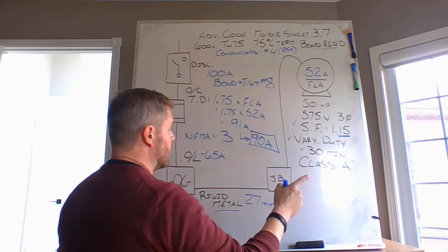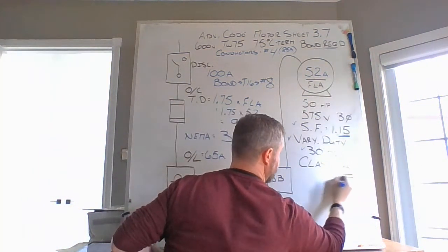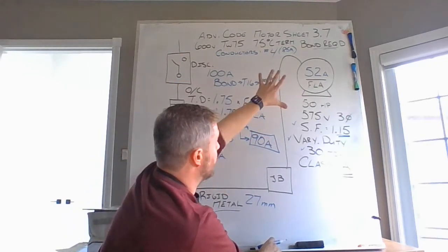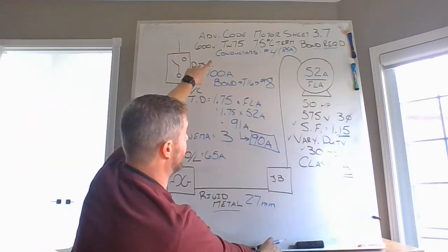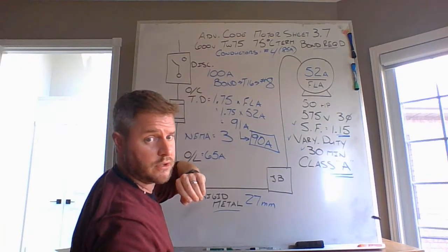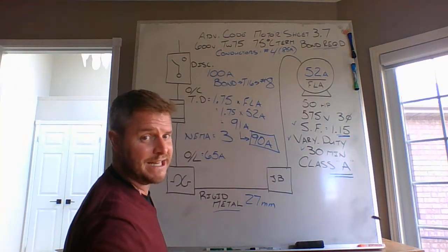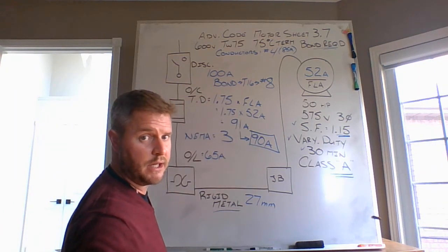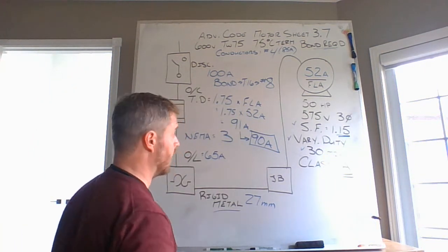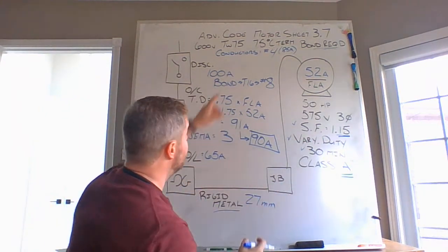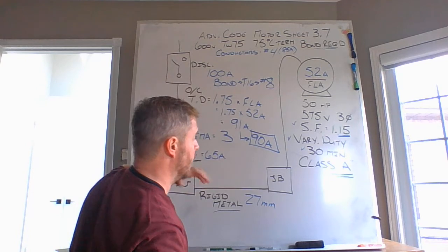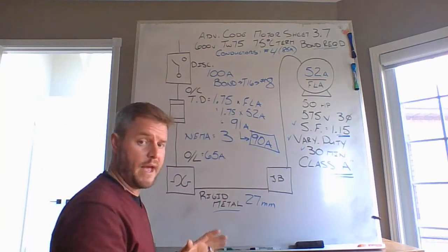Okay. The reason why I can't use the 90 degrees Celsius ampacity for that Class A motor is that all of my termination temperatures are based on 75 degrees Celsius, and so is my conductor. So I cannot use the 90% rule for that calculation because I'm not running T90s. I'm not running RW90 XLPE. I'm running TW75. I can't get away with that 90 degrees Celsius ampacity because I'm not using 90 degrees Celsius wire. All right? So just take a second and record that information.